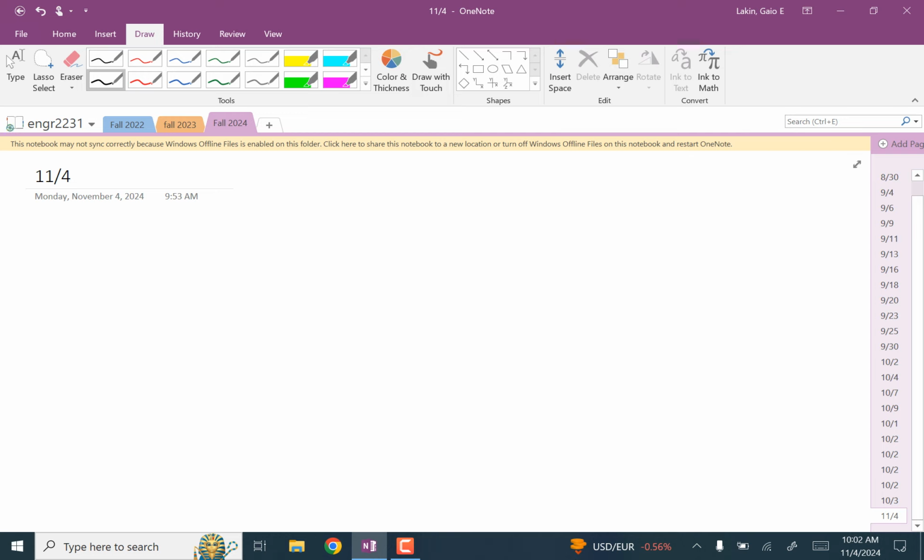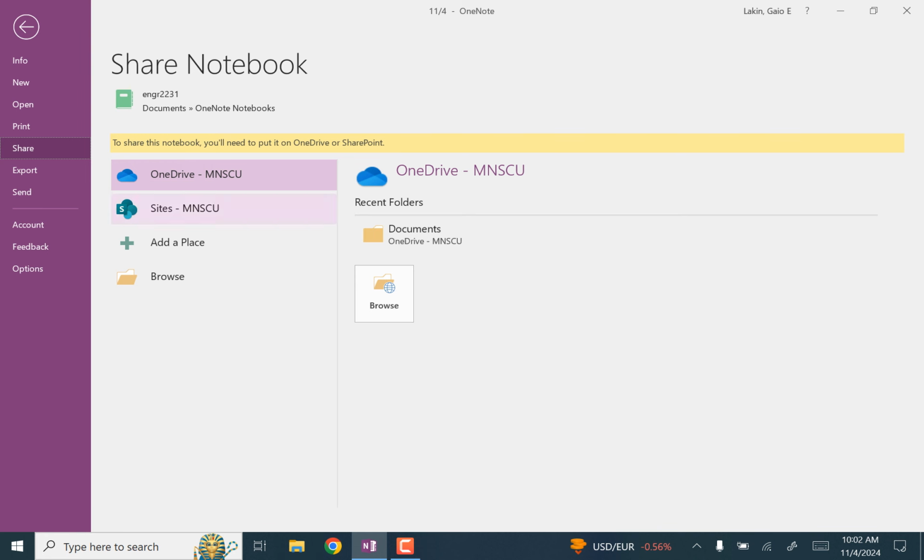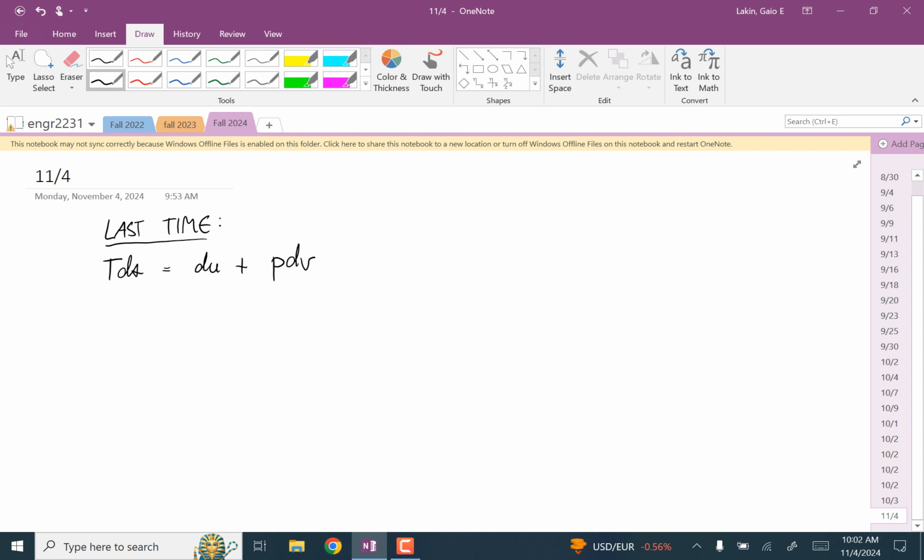So last time, Wednesday, I brought up the TdS equations. So we have TdS is equal to du plus PdV. And remember, these are all intensive, dependent on mass. Yeah, they're all per mass, exactly. So these are all the values that you can find in a table. And then the other one is TdS is equal to dh minus VdP.